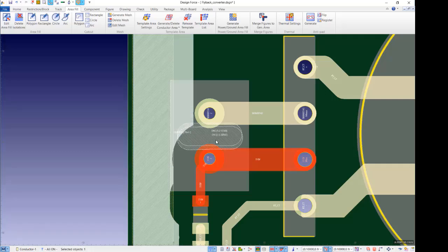But I know I got an issue here. So what I'm going to do, I'm going to purposely put a slot that's too small. So when I run the DRC, it'll show that the path the creepage is going to take is to the edge of the slot, around the slot itself and onto the conductor, or to the slot and then through the PCB surfaces to the bottom side and then to the conductive pad on the bottom.